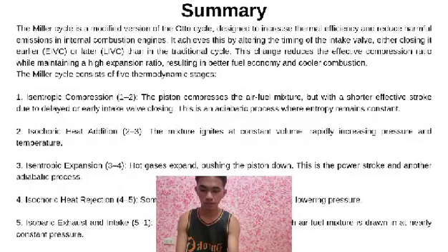So, to summarize, the Miller cycle is a modified version of the Otto cycle that adjusts intake valve timing to achieve better fuel efficiency and lower emissions. Its 5 stages: compression, combustion, expansion, heat rejection, and intake and exhaust form a continuous, highly efficient engine process. By lowering the compression ratio and extending the expansion stroke, the Miller cycle maximizes energy use while minimizing waste and environmental impact. Thank you for your attention, and we are now open to any questions you may have.